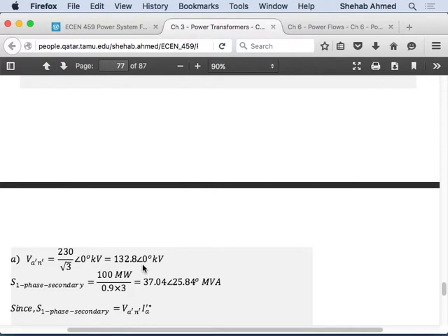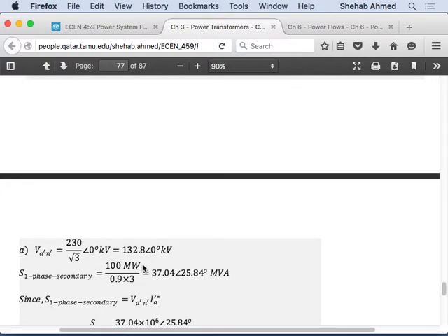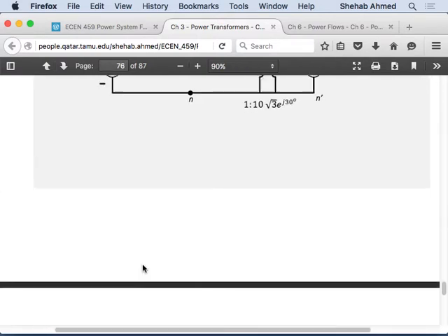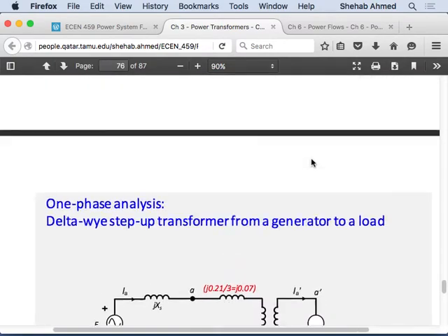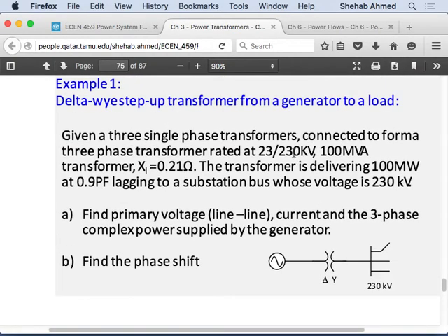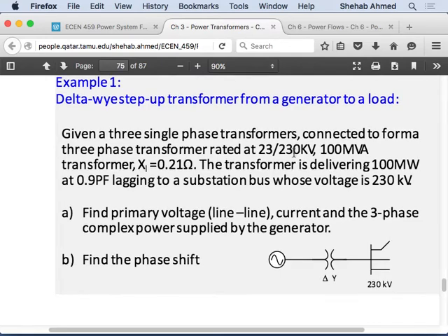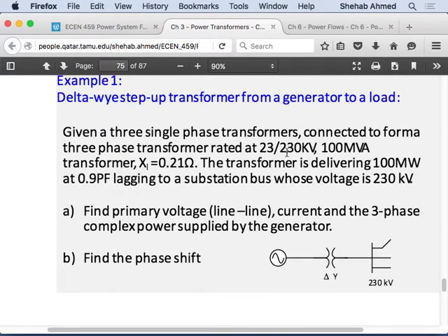Which sort of defies the fact that they assumed it was the single phase transformer's terminal voltages initially, right? So there's a typo, there's a problem with this. You cannot use a 10 here and then assume that the 230 is your phase voltage, right? So here they assume 230 over 23 was the phase voltage of the single phase transformer. So the ratio between the primary and secondary was 10.